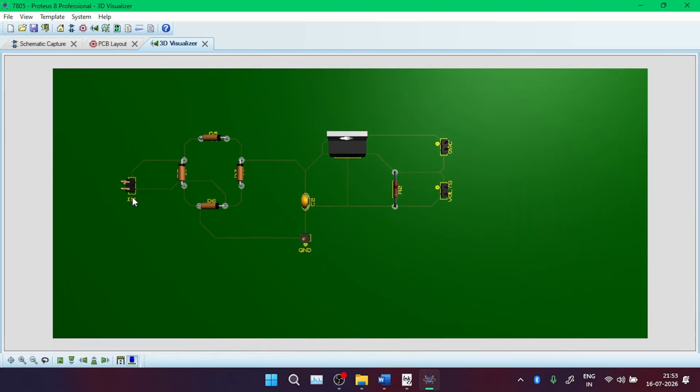I'm going to give the transformer inputs from here, and from here this is going to be rectified, and from here it's going to the C2 along with the regulator output, and from here itself I'm going to take a point so that I can check the output. Better we keep another point here for checking the output at the transformer, but that's completely your choice.